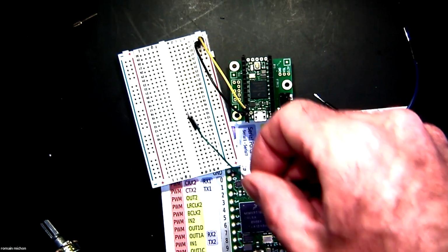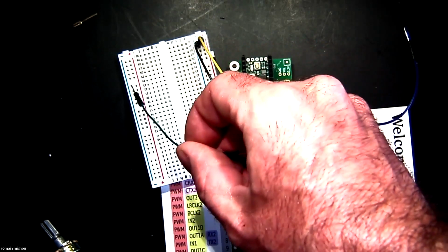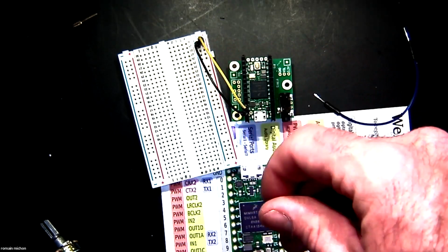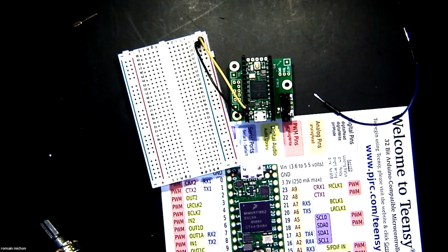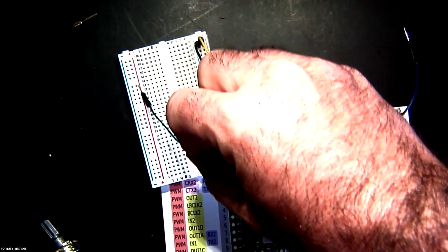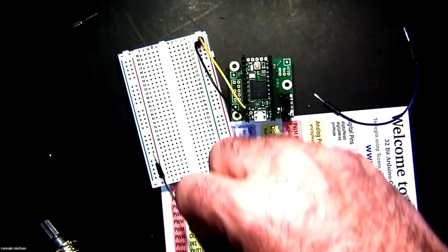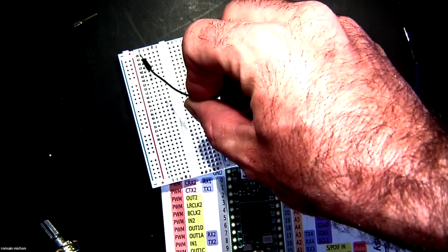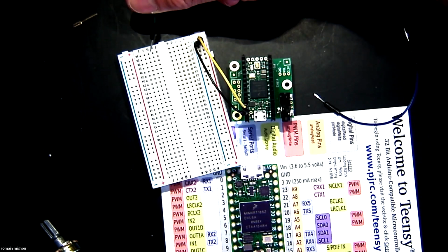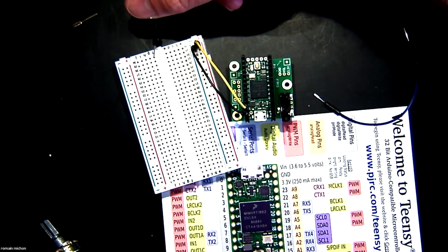Okay, so for the breadboard, so far we talked about the lines that are on the extremities of the breadboard. We haven't talked about these lines. The lines at the center of the breadboard are wired in the other direction. So where these lines are wired in this direction, these lines are actually wired like this. This pin is connected to this pin, is connected to this pin, which is connected to this pin. And they're not connected on both sides.